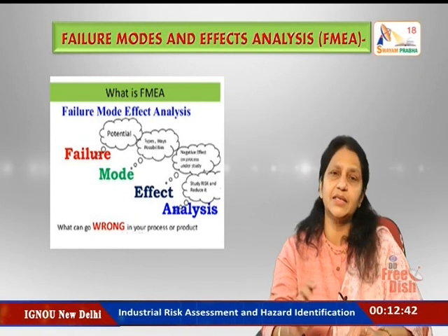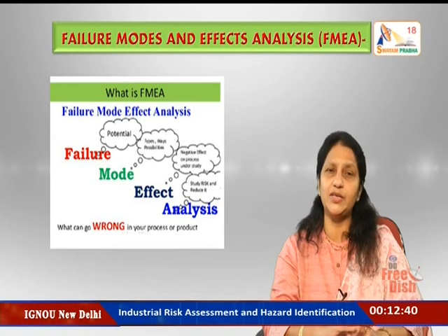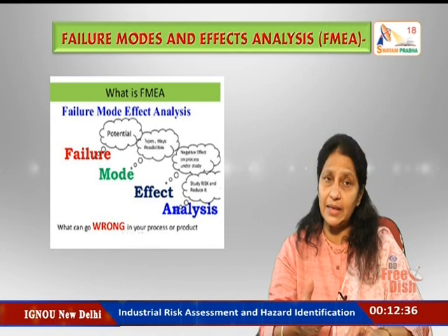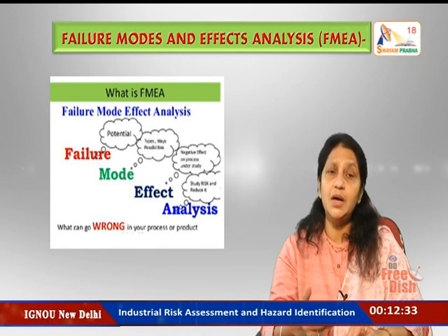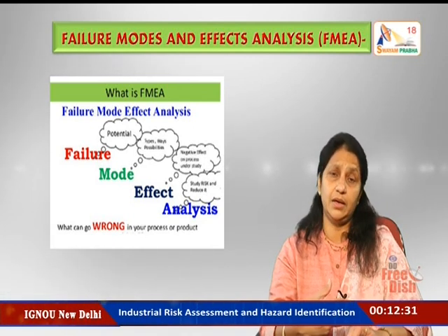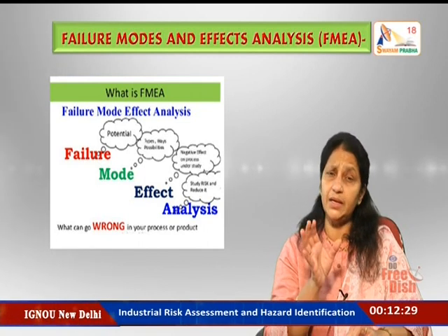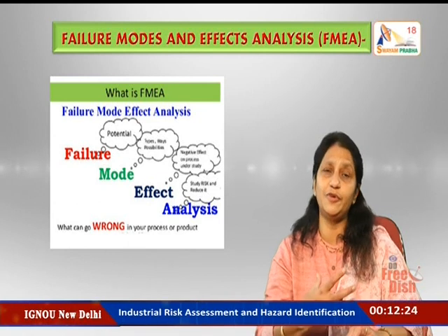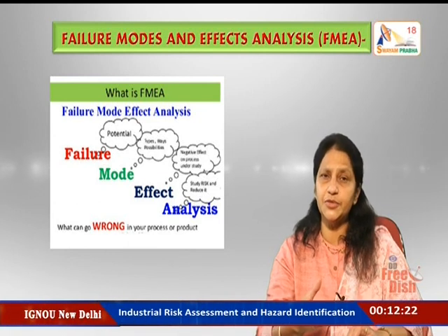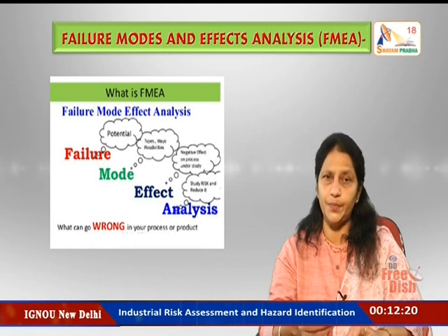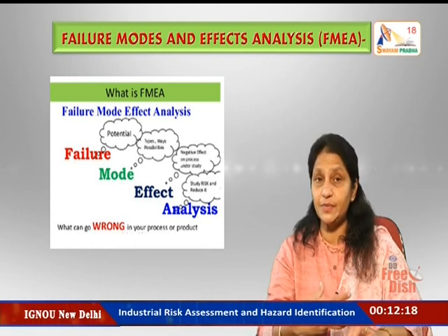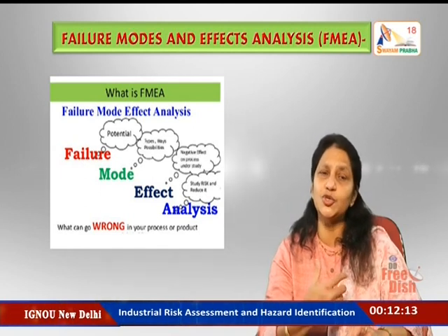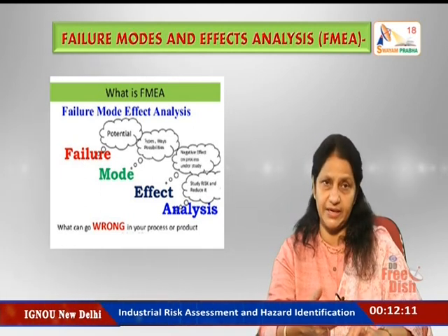A detailed description of the process is initially required, so that it can be broken down into either a functional, hierarchical, or reliability block diagram. The assessment team needs a detailed description of the various actions performed by each section, like a description of their modes of success or failure, and should establish the basic principles and the purposes of the study. The purpose and scope of the assessment need to be stated.